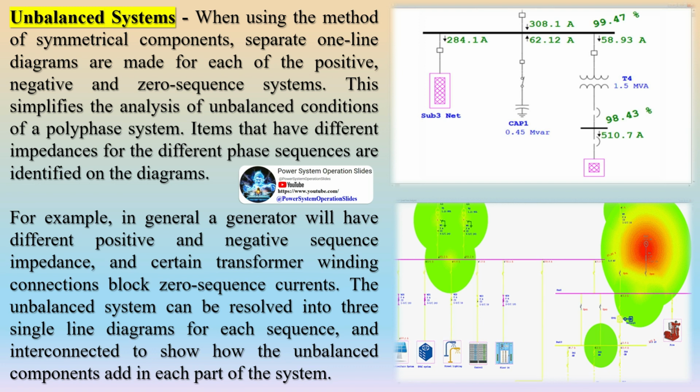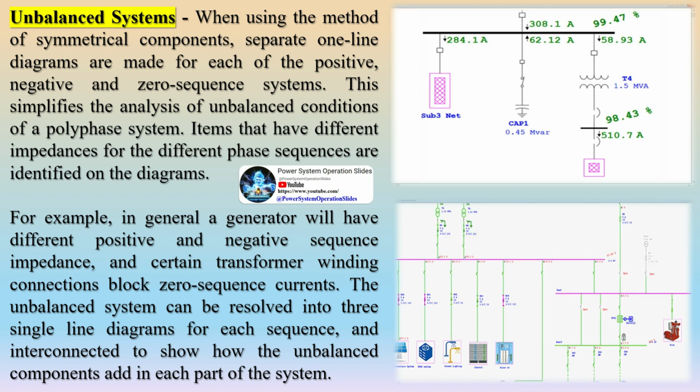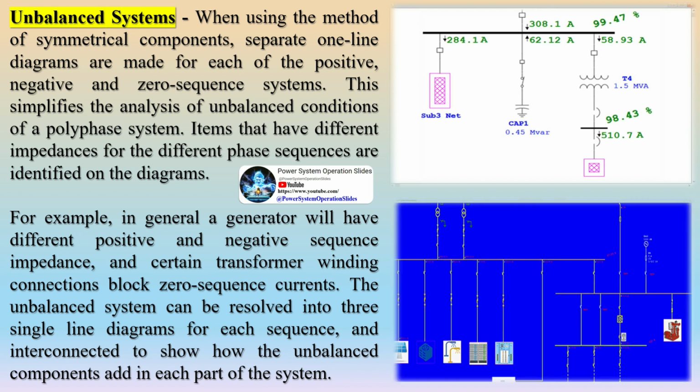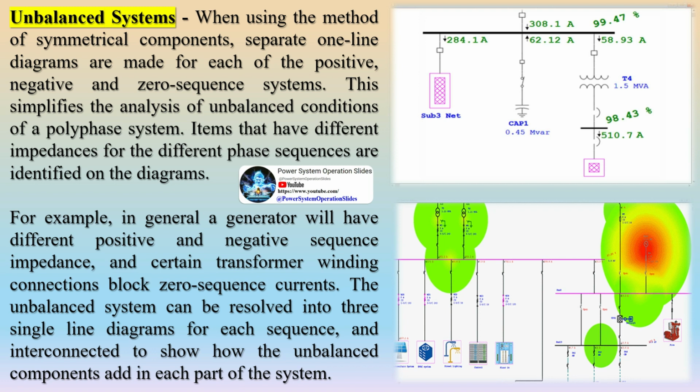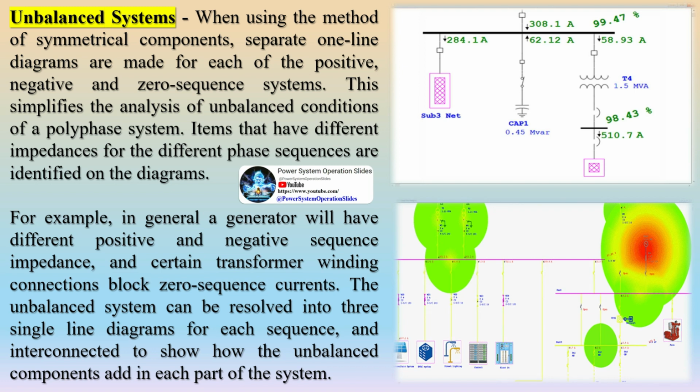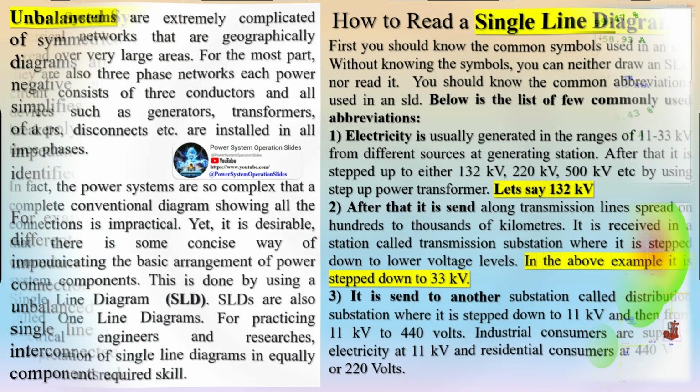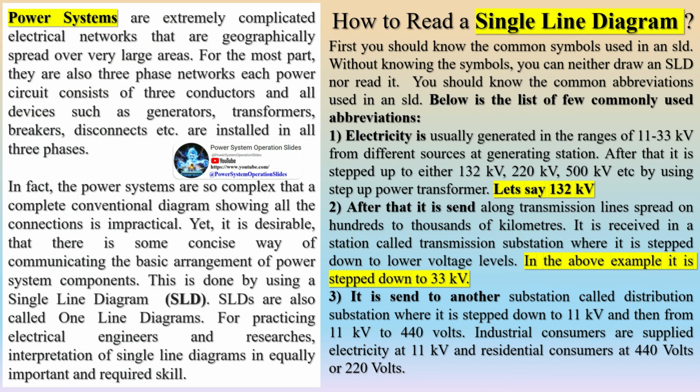In power engineering, a single-line diagram (SLD), also sometimes called a one-line diagram, is the simplest symbolic representation of an electric power system. A single line in the diagram typically corresponds to more than one physical conductor. In a direct current system, the line includes the supply and return paths. In a three-phase system, the line represents all three phases. The conductors are both supply and return due to the nature of the alternating current circuits.